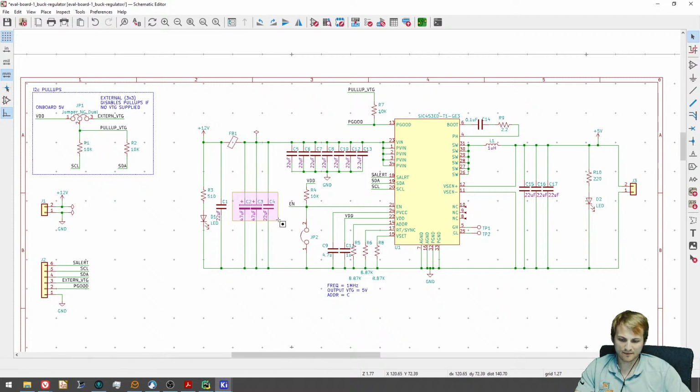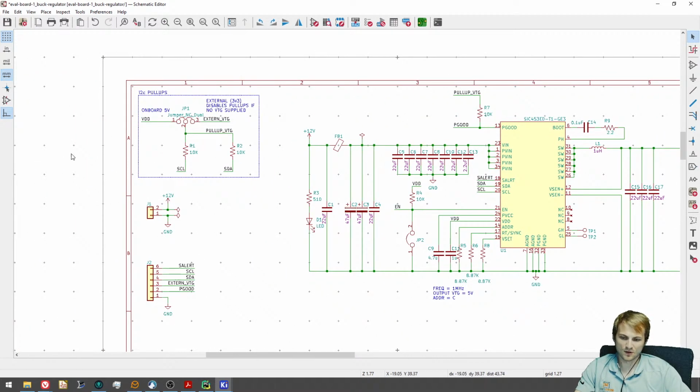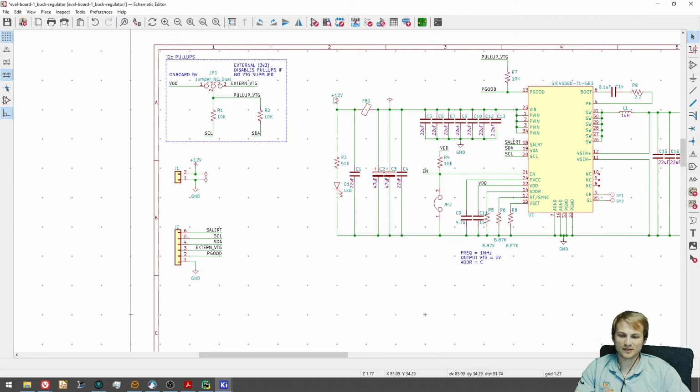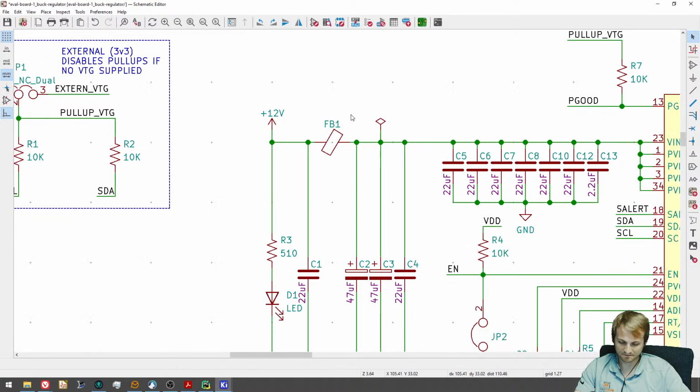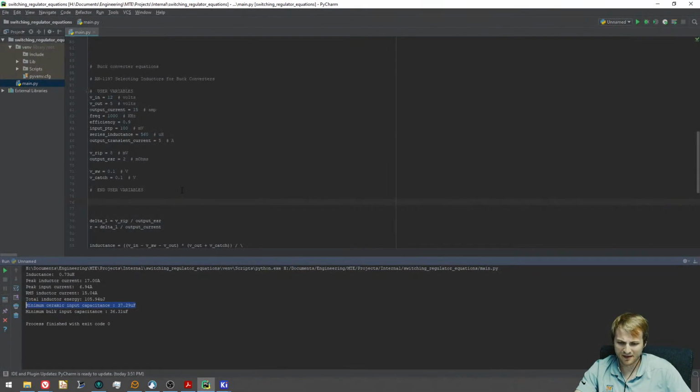And if you don't have any bulk capacitors here, the only place that they can draw current from is from your wall supply. And since you have an inductor on that wire, it most likely isn't going to be able to do that. So your 12 volt supply or your 12 volt rail quickly becomes 11, 10, 9 volts, and bad stuff happens, a lot of noise. You can get brownouts and all sorts of bad stuff.